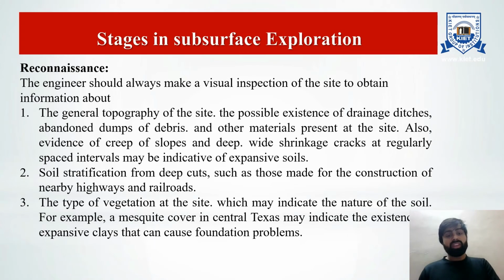Also, evidence of creep of slope and deep, wide shrinkage cracks at regular spaced intervals may be indicative of expansive soil. And to obtain the information about the soil stratification from deep cuts such as those made for the construction of nearby highways and railroads.